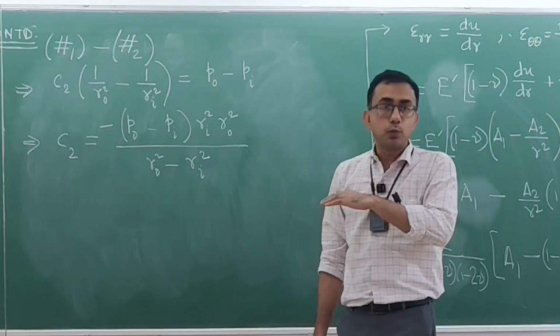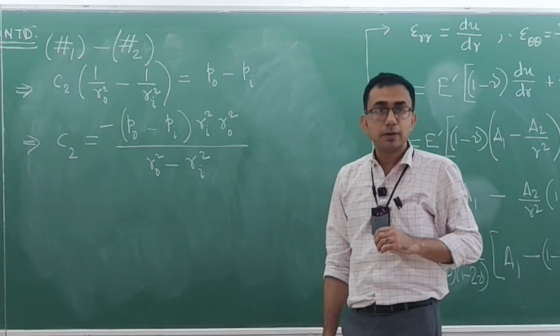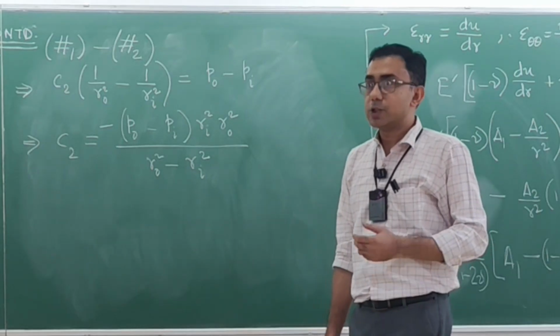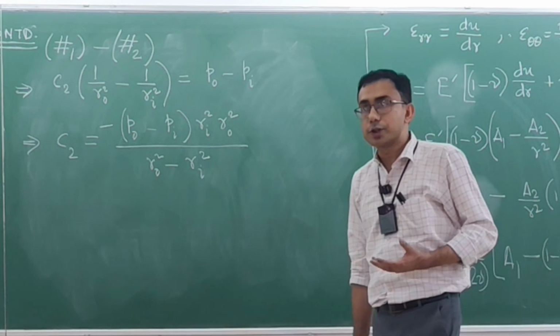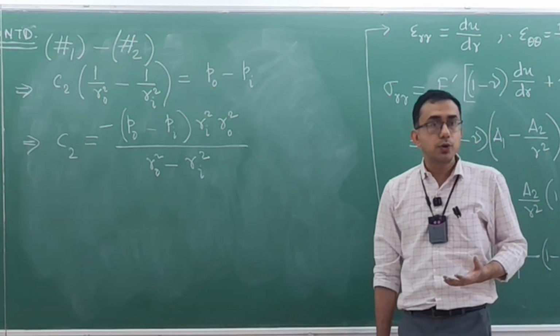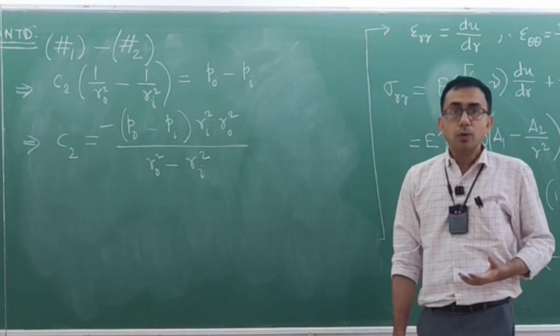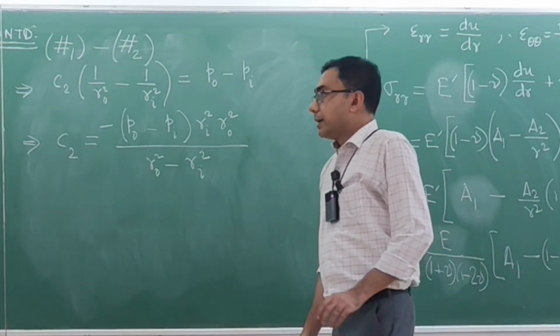So the entire thing was within the scope of plane strain. Remember, if you look back at your notes, I made a big deal about it, that this was the case of plane strain, where epsilon zz is equal to 0, epsilon z theta equal to 0, and epsilon zr equal to 0. But now I want to discuss a situation where we'll have plane stress.